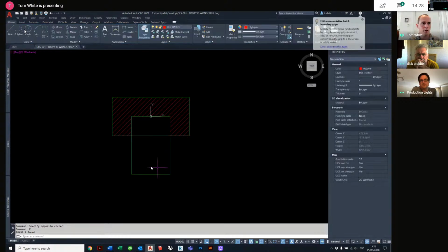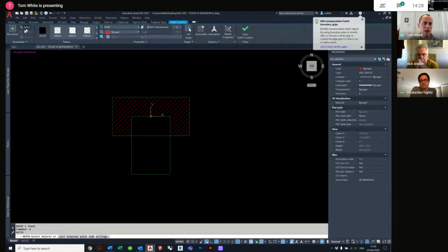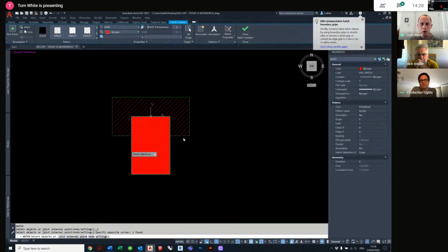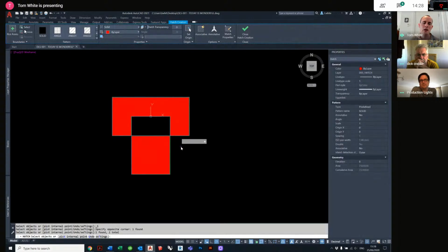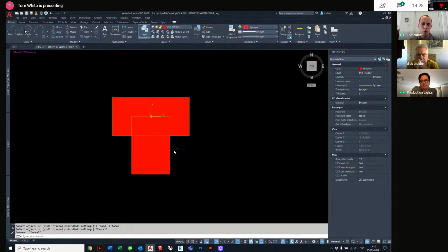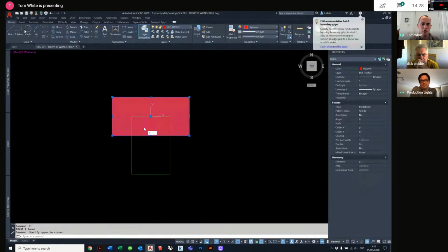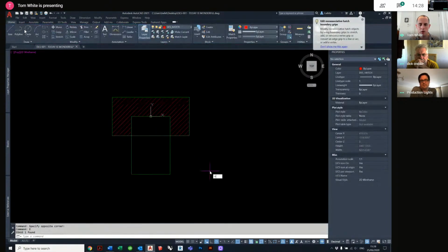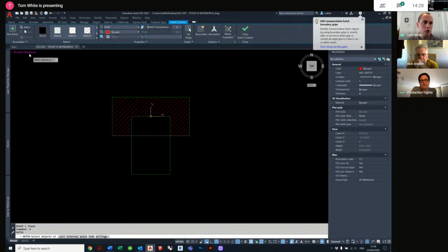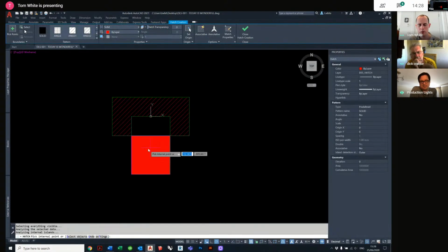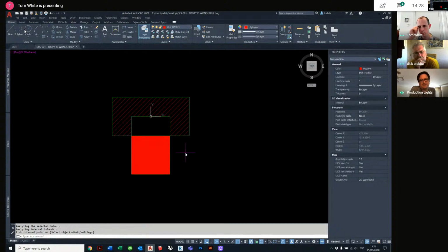You can, and I don't know if it's going to work, if I do the hatch command, I can select multiple objects and it might do what I desire, but it's not really doing what I desire. So more often than not, I would try my best to use the pick point. Dom, do you have a preference? Unless it's a single thing, it's pick point, because then you know where it's going, and you don't have to go back and do it again.